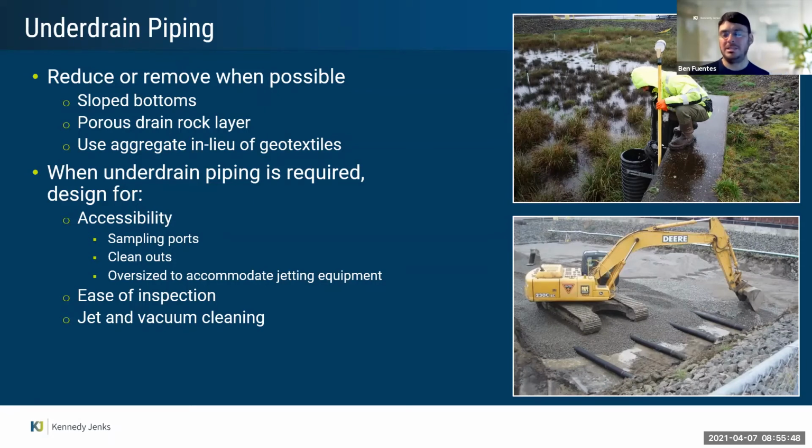But when that just isn't feasible for whatever reason, and you want to make sure that water is getting collected and out for proper drainage, it's important that you're designing your underdrain system for full accessibility for long-term maintenance. That there are cleanouts sized appropriately at sufficient intervals, avoiding blind taps, where you won't have a point of access for cleaning in case solids get built up and start to clog the pipes.